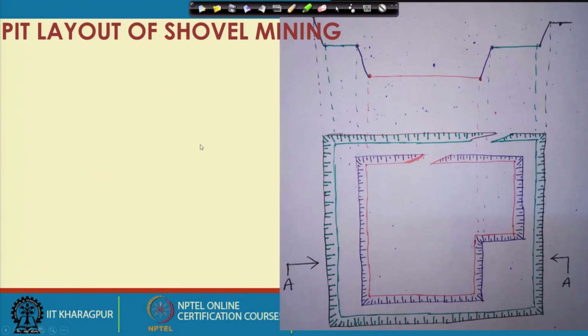This is a rectangular pit. If the pit is moving this way, we provide an excavation at this position, then gradually extend it in this direction. What is the benefit? The benefit is that our shovel has to swing only 90 degrees in this case. When it reaches up to this, we will do the same thing at this position and extend it gradually in this direction. This is the way we carry out the extension of the pit.